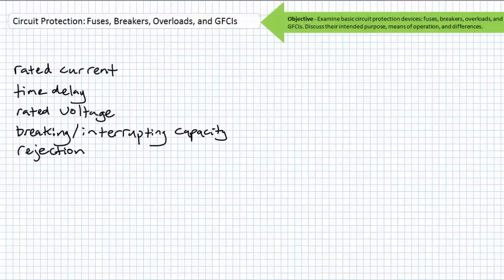Once the system is properly shut down and properly locked and tagged out, only then can the fuse holder be opened and the fuse inspected and/or replaced. In addition to following proper lockout and tagout procedures, keeping the fuses with you while you perform a maintenance procedure establishes yet another layer of protection, preventing the inadvertent startup of equipment.